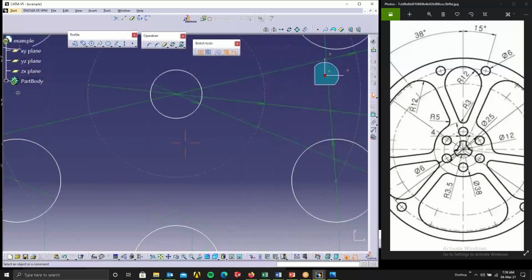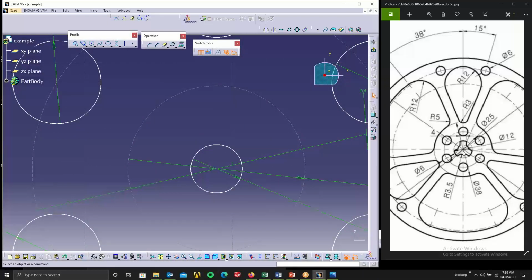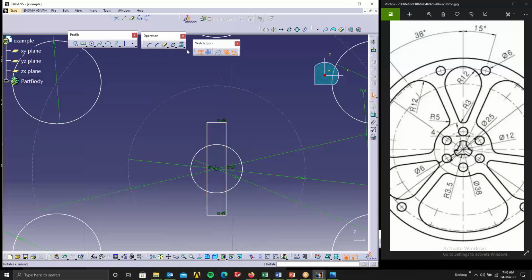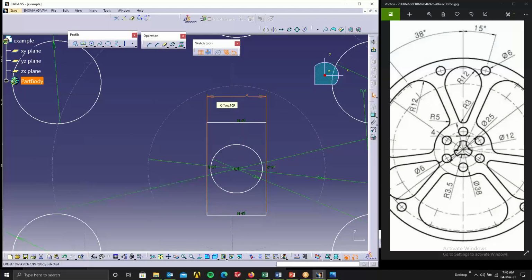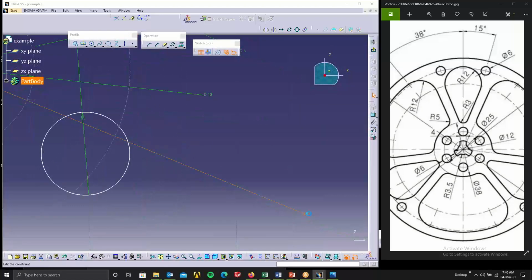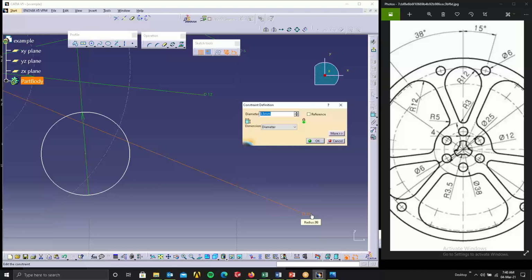And in this total circle, here they have given a rectangle of 4. So take your usual rectangle command. Where is rectangle command? Here it is there. So take center point rectangle. Select the center point. Double click. Just select these two sides. Give how much? 4 mm is too much. This is radius 3.5. So that is basically diameter 7. Enter.